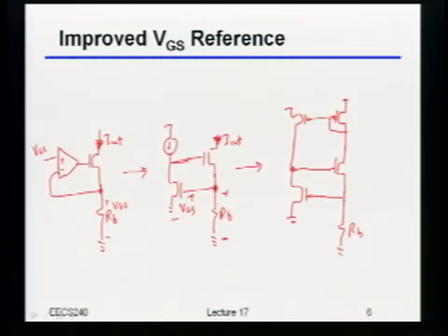So anytime you do one of these things, by the way, this is a real so-called VGS-based reference. Anytime you do one of those things, you'd better be careful that it actually will start the way you want it to. Okay, so we'll see that more in a second. We'll actually see an example startup circuit. But with all these reference circuits, just keep in mind, somewhere at the beginning of time, somebody usually needs to kick it.